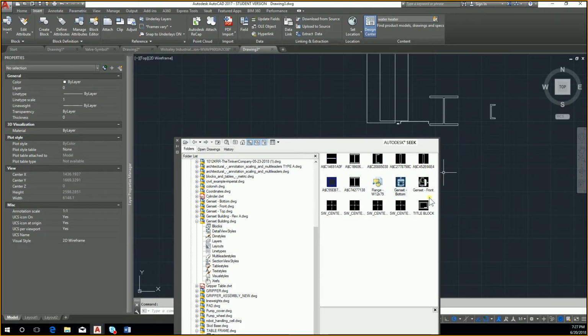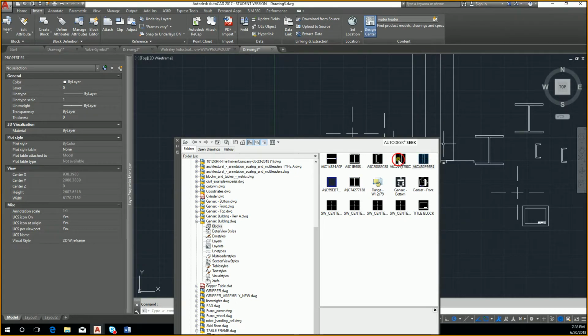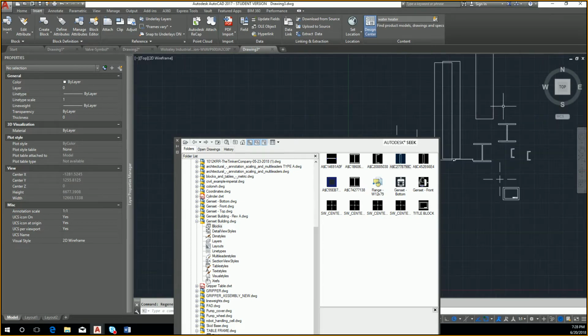This is the Design Center. So whatever size that I had saved it though, that is going to become a scale. So that's why a lot of times it's very important to draw everything one-to-one in your model space. But as you can see, once you've done one design, you're able to reuse all that work. So that's the strength of your design center. It's not about always having to draw everything from scratch.